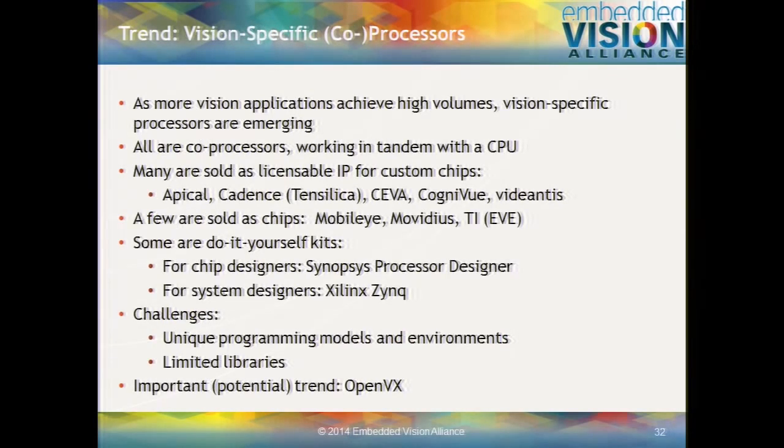You asked a few minutes ago about DSPs optimized for vision. And in fact, there are roughly 8 or 10 products out there that are DSP processors, but really tuned for vision applications. Most of them are not chips. Most of them are silicon intellectual property cores, the same business model that ARM uses, where they don't make the chips. They provide the processor design to chip manufacturers, who then implement that processor on their SoC alongside whatever other processors and buses and memory, et cetera, they need for their application.